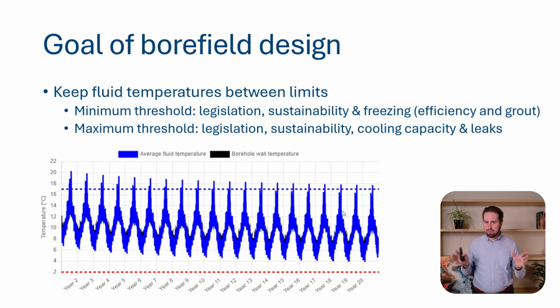So that's the philosophy of design. We want to stay within certain limits. These can vary a little bit from case to case, from country to country, but in the end, there is always the goal of staying between limits. Now, we want to do that by borefield design. So determining the depth and the number of boreholes, as well as other parameters we will discuss later in this course, but the goal is to determine the required borefield size such that we stay within these limits.